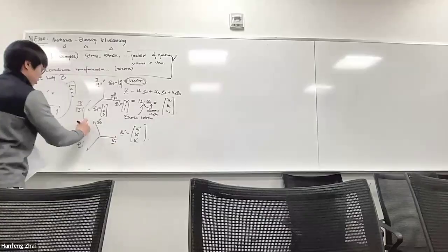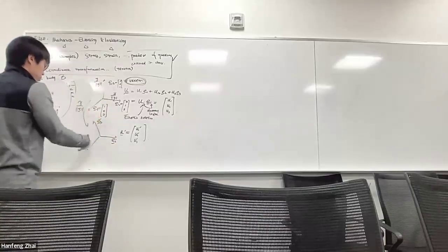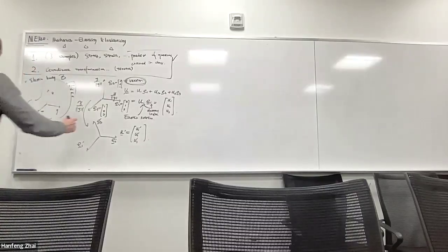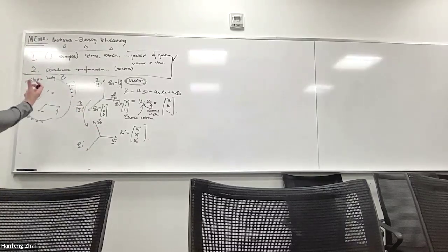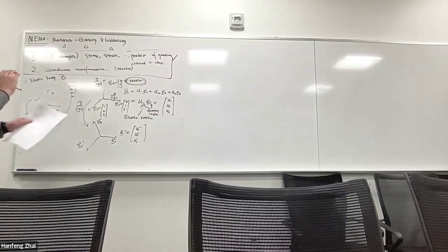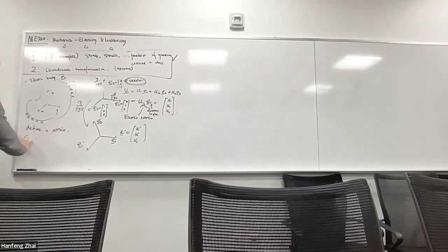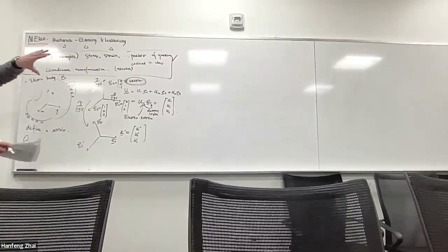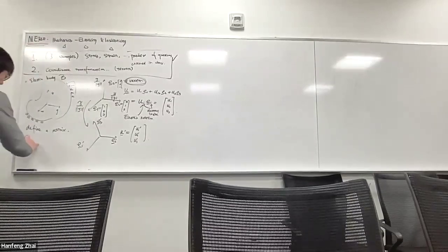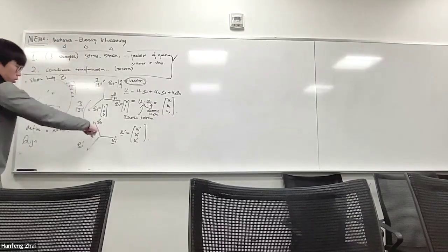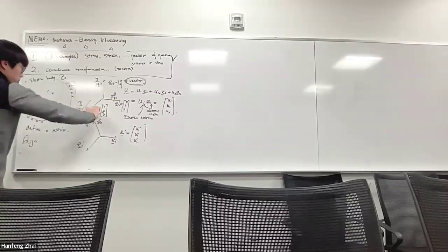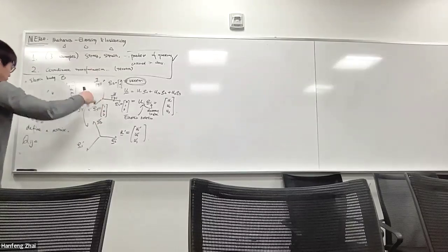So after the coordinate transform from E1, E2, E3 to E1 prime, E2 prime, E3 prime, the origin is fixed. How do we characterize this operation of transformation? We can define a matrix called Q, which is the rotation matrix, and characterize the rotation from one coordinate system to the other. It has 2 indices i and j, and is the dot product of the unit vector of the new coordinate system times the unit vector of the old coordinate system.